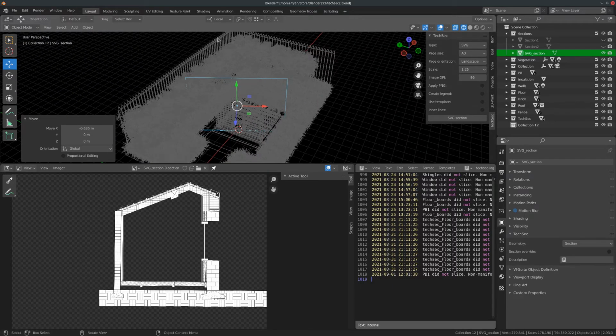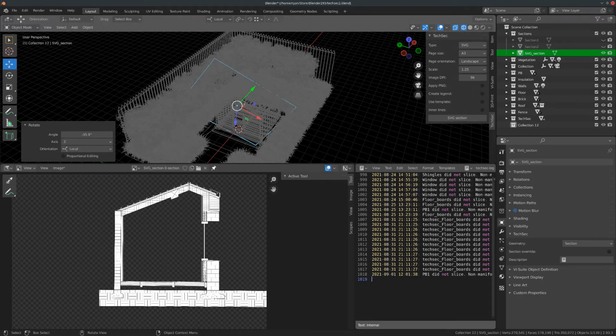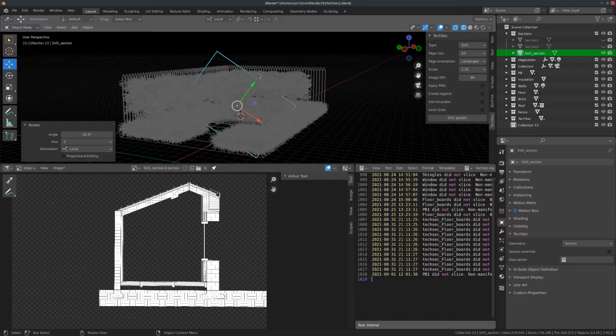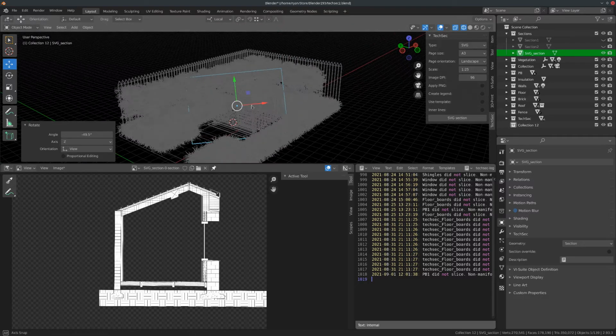The importance of the local axis is that if I was to rotate this plane, my local y-axis direction still aligns with the top, or what you might consider to be the top of this section. So it means that you can rotate this section however you want, and the local y always points to this edge here, and this edge will represent the top of the page.